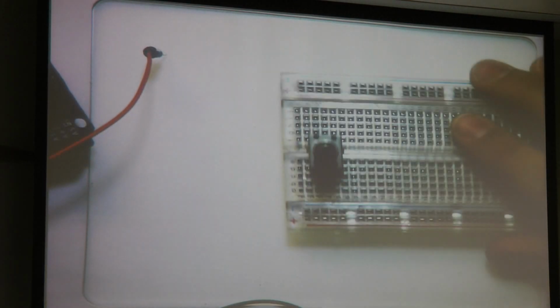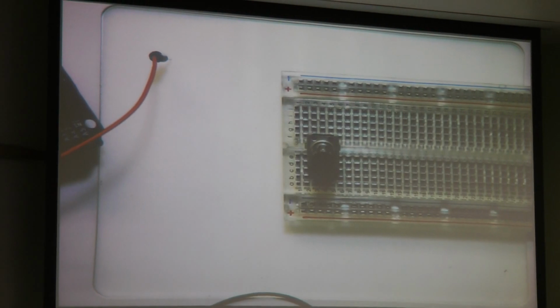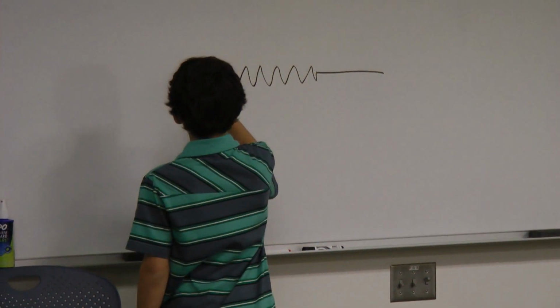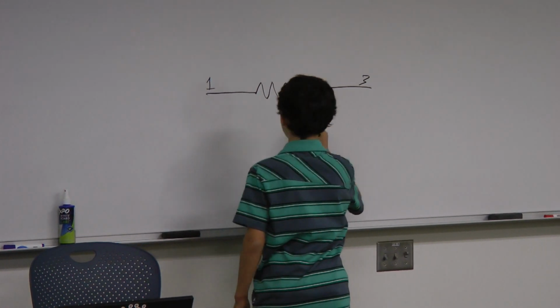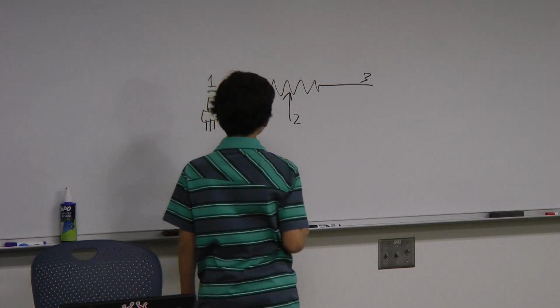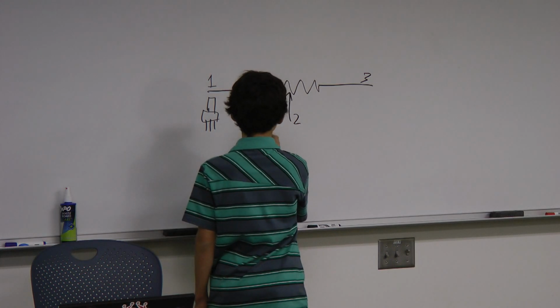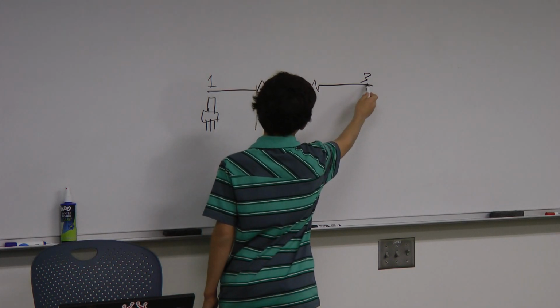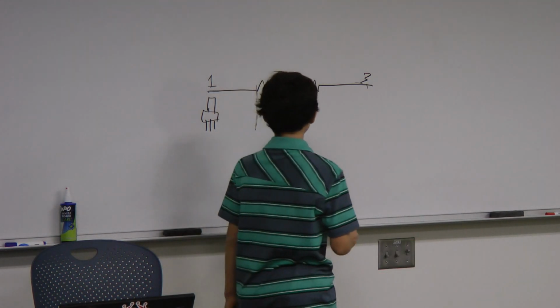The 2 outer pins are the same resistance. So think of a potentiometer as being, here's your potentiometer and here's your resistor. I'm drawing it extra long for demonstration purposes. This is, say, pin 1, this is pin 3, and the wiper is pin 2. So on it we will have 3 pins and then our knob coming out of it. When you turn the knob, you move this wiper. When you turn it all the way one way, it's connected to pin 1, but pin 3 has the highest resistance, 10 kilo ohms in this case. This is a 10 kilo ohm pot, or 10,000 ohms.